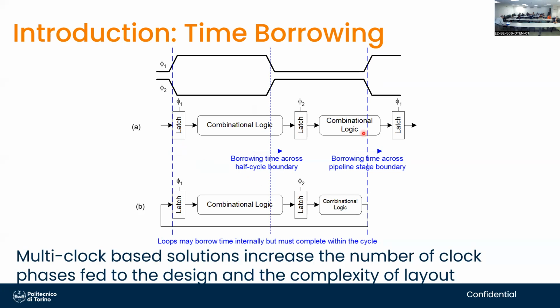If you are in an acyclic pipeline, like the execution pipeline of a microprocessor, you can be more flexible because you eventually have to pay back all that you borrowed, but it will be much later. And there are timing constraints that have to be satisfied, and there are very expensive software tools, about $500,000 to $1 million per seat, that allow you to do that for circuits with billions, tens of billions of gates and billions of flip-flops.